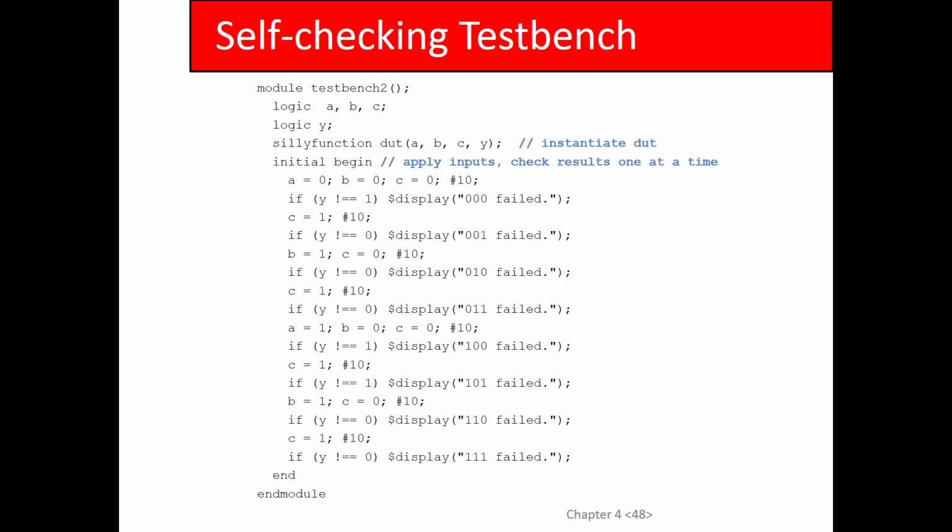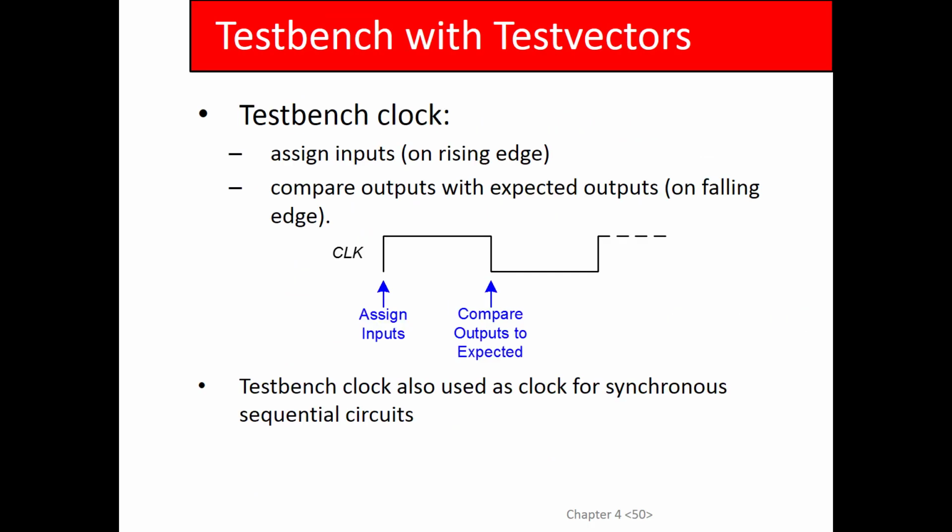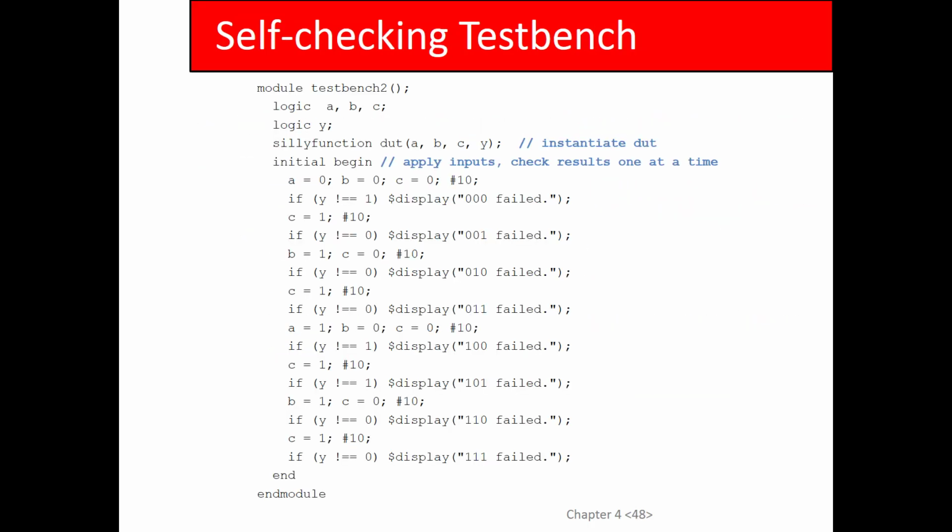So that's what these test vectors are. You can design a test bench that runs through a test vector file and just does all the tests in the test vector kind of mindlessly. And if you do that, then the problem is how do you synchronize things? How do you make sure that the inputs are sent into your design under test, and then the outputs are evaluated after having advanced the time?